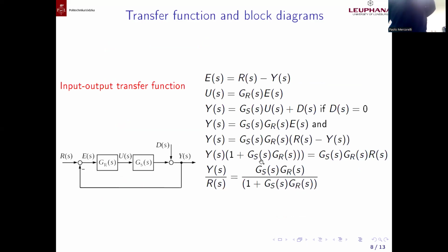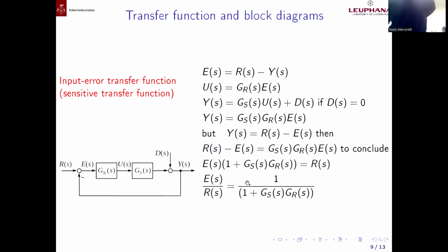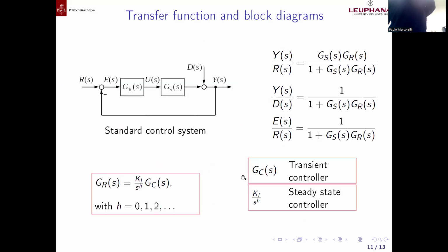is if you calculate one, this, for instance, no, this one. To calculate this is not so difficult if you apply, do you remember, the rule: in the numerator, you have to put what I find as a transfer function between the input and the output. This means I have a transfer function 1 between this signal here and this signal here. And the denominator is exactly a loop structure, which I told you last time.